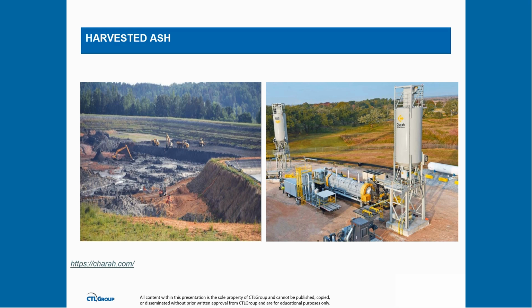However, this harvested ash has a lot of challenges, like high moisture content, high LOI, presence of free lime or excess alkalis or sulfur, contamination of ash with salt, soil, and organic materials, and the heterogeneity in the fly ash properties within a landfill or pond.